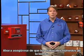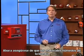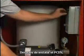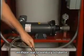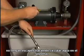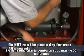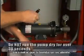Now you need to make sure that the wetted materials of the pump are suitable for the liquid being pumped. After the PCDS is installed, check the pump and piping for leaks by pumping water through the system. Do not run the pump dry for over 30 seconds to avoid burning out the pump.